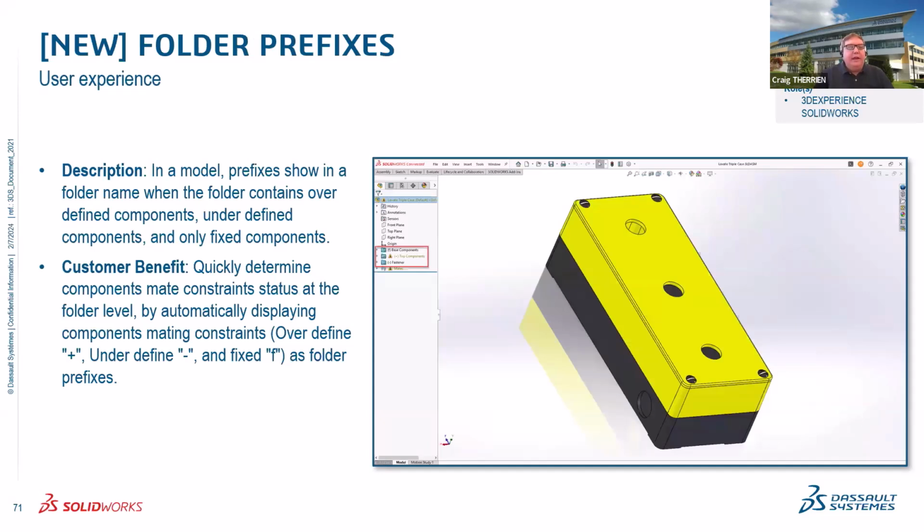When you're looking at an assembly and you have folders, when you look down at the folders, you'll be able to tell very quickly whether you have components that are underdefined, fixed, or overdefined in those folders. Next.